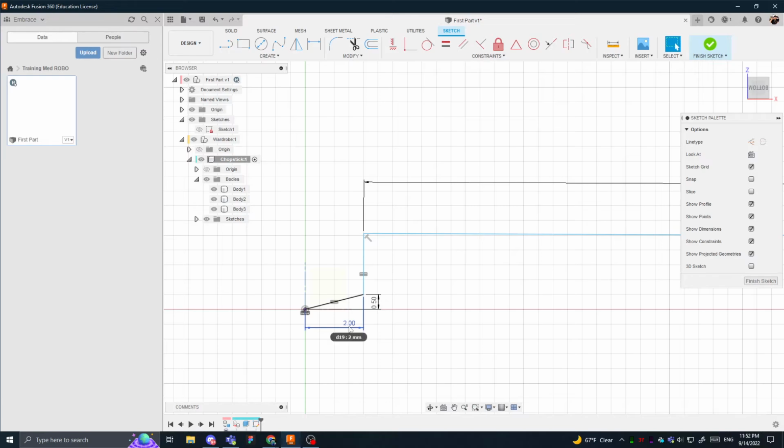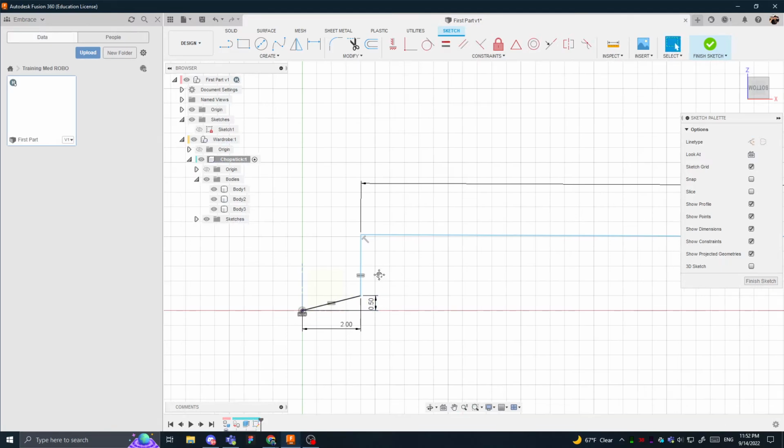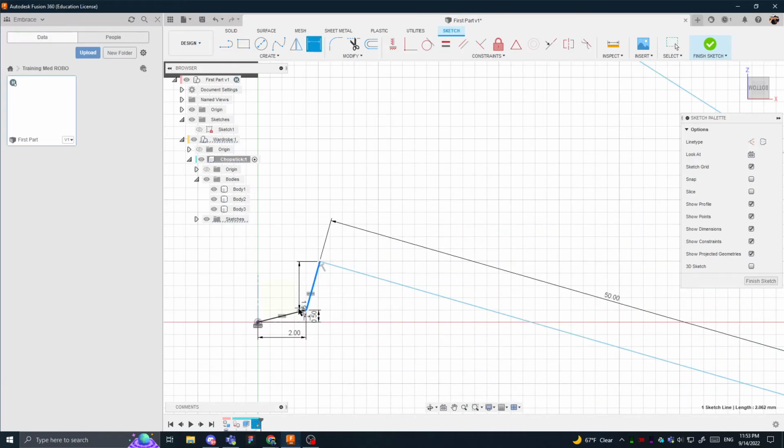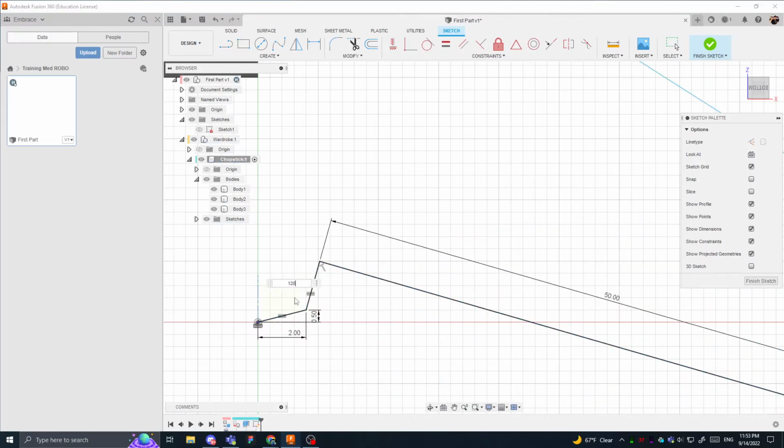You know, you got the adjacent and the opposite. Therefore, the hypotenuse is determined, and you have the angle because of its tangent. If you do tan of opposite over adjacent, you got the angle. Therefore, you only need those to determine the angle, and therefore I can't change even the length. That's fully dimensioned. Now let's talk about the angle between here and here, and I'll say 120.